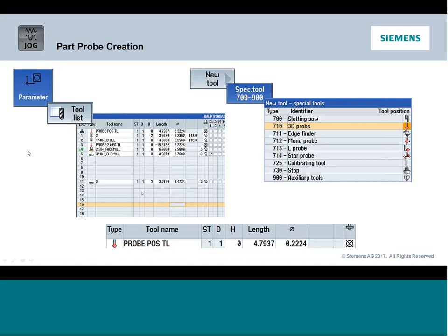But when it comes to touch probe for tool probes, or when it comes to part probes like we've talked about over the last hour and a half, you can use anybody's part probe. Doesn't matter. You're just going to go through our calibration routine, and that's the trick.